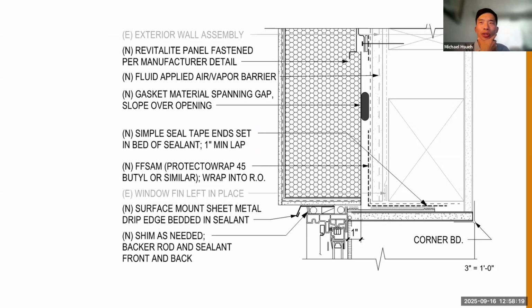For the roof panels, this was a little bit before my involvement in the project, but I think there was a lot less conversation around those. I think they zeroed in a little more directly on using these existing refrigerated warehouse panels that were already available. Part of the advantage is they're polyiso insulation with sheet metal and very light. And that's another factor in this project: as light as you can go is what you had to do.